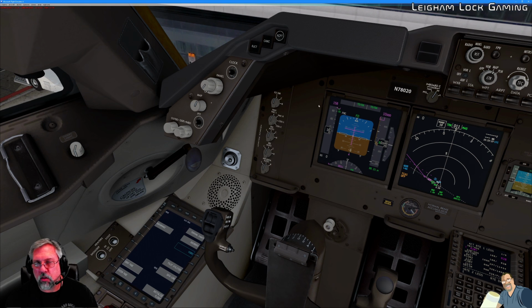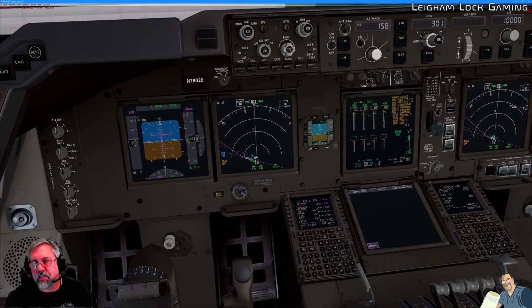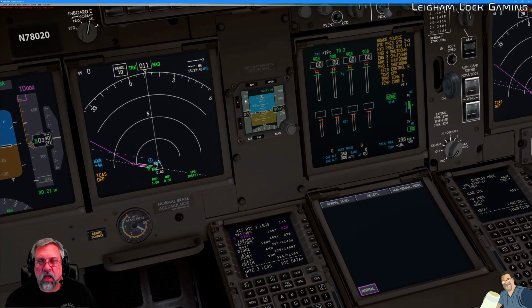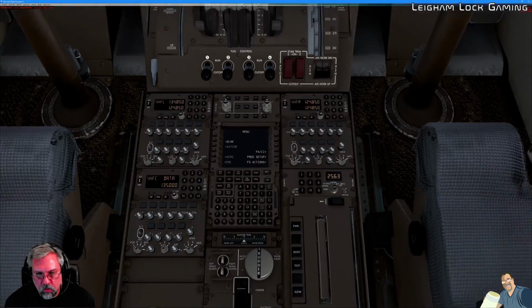The captain also is going to spot check the integrated standby attitude indicator. It's integrated, so it's matching our barometric pressure. Everything looks good. Attitude looks correct. No other indications for approach, so we don't have any glide slope or localizer information on the display, so that is fine. The plus and minus basically just control the brightness of this particular display. That's all they do. Now we want to look at the controls. Oh, wrong one. Let's go here.